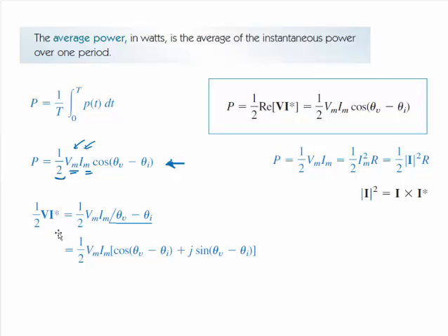We can also note that if we are going to multiply a phasor for voltage times a phasor for current, in phasor notation it's written this way, which is using our Euler's identity, we get this part, and then if you take the real part, you come back to the actual answer. So actually the point is the real answer is real numbers. The real answer is not a complex number. Phasor notation is a way for us to keep track of phases, but in the end, if we want a real answer, we have to take the real part.